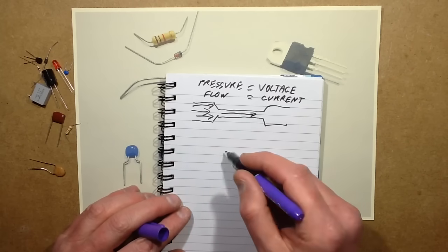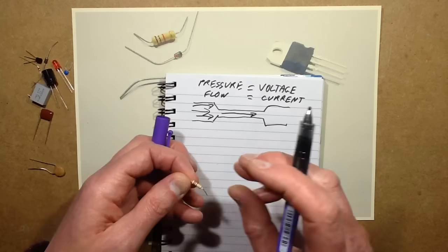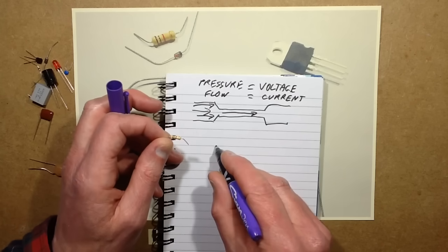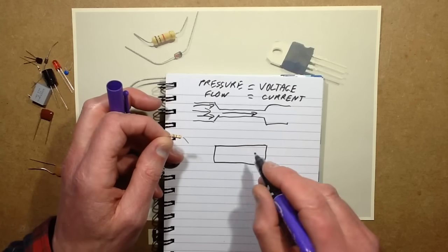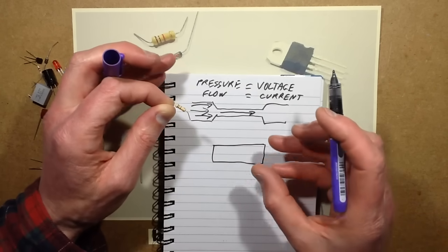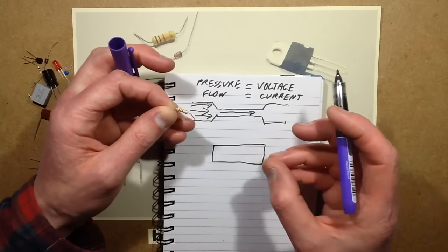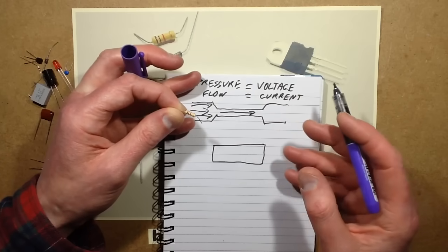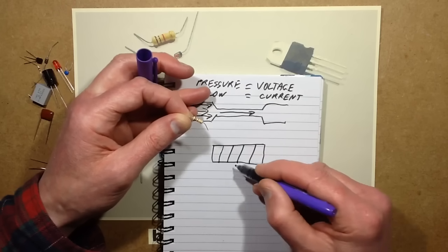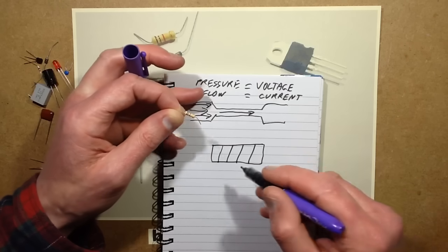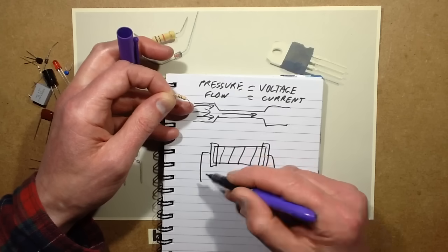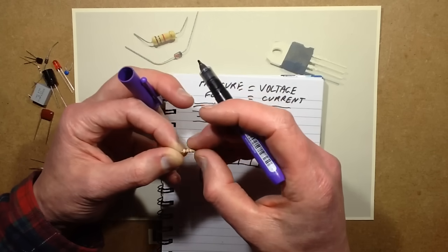Now the construction of a resistor is usually, in the case of these ones, this is a carbon film resistor. And you get metal film, carbon film, wire wound, but one of the most common is just carbon film or the metal film. And they have a little ceramic tube which is coated with either the metallized coating or a carbon coating up to a specific thickness. And the thicker the carbon coating on it and the type of the composition they're putting on it, the more conductive it will be. But then they can fine-tune that. They actually cut a spiral round it, and that creates a long thin path of the carbon, and that increases the value of the resistance. And once they've done that, they put a metal cap in the end with the leads coming off, and they dip it in a sort of I suppose it's a lacquer really.